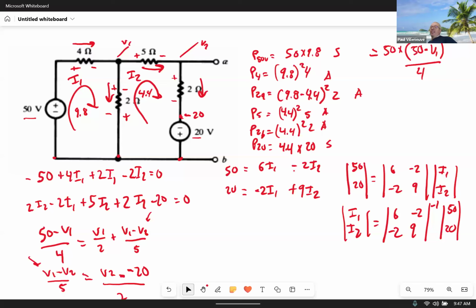So the current there takes a little more work. I actually have to figure out what the current is. Yep. So I'm trying to solve for the current out of that 50 volt source. So I'm taking this voltage here, subtracting that voltage, and dividing by the 4 ohm resistor. So I did 50, which is the voltage in the lower point.